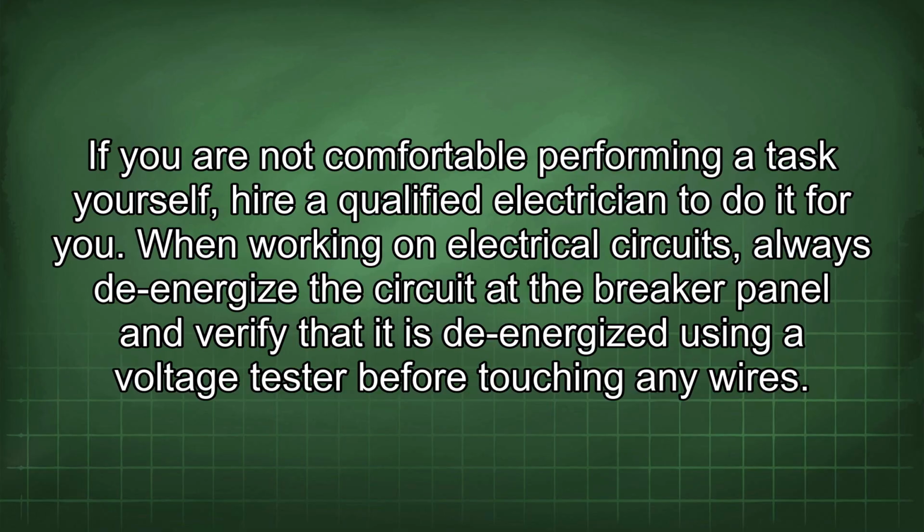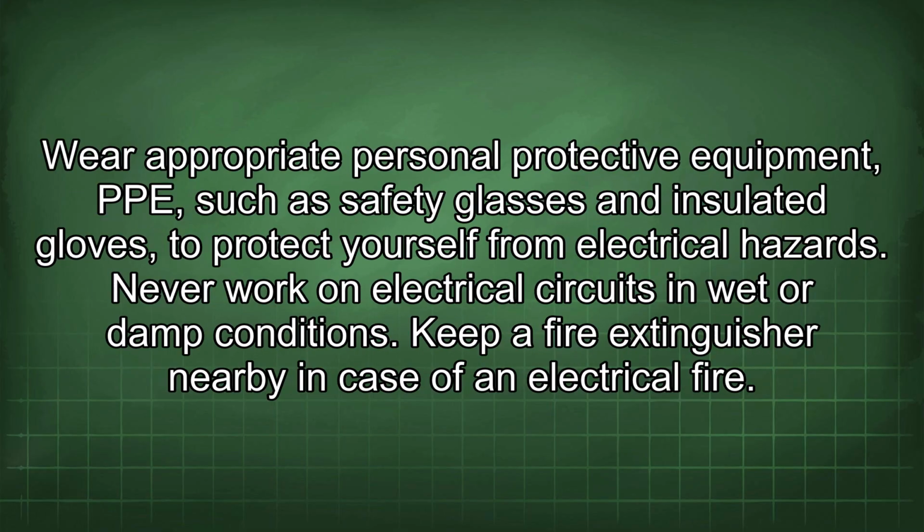When working on electrical circuits, always de-energize the circuit at the breaker panel and verify that it is de-energized using a voltage tester before touching any wires. Wear appropriate personal protective equipment, PPE, such as safety glasses and insulated gloves, to protect yourself from electrical hazards. Never work on electrical circuits in wet or damp conditions. Keep a fire extinguisher nearby in case of an electrical fire.